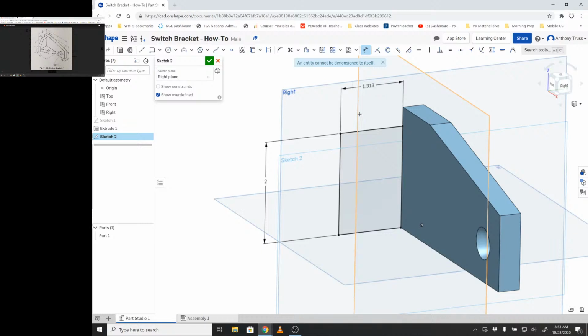Okay. So at this moment, we have most of what we need. We know we need to use 30 degree and then the 7/8. The 7/8, once again, is the construction line that represents where that 30 degree line happens. So you're going to create a horizontal line, just like I showed you. We're not going to snap to the middle.